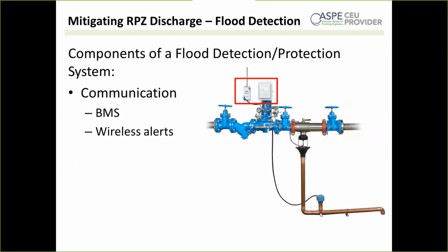Are the shutdown valves FM approved? UL and FM approved. I want to say, I know the one that you're seeing on your screen right now is not. For those of you who don't deal with fire, FM is typically a fire certification. Because I would never personally put a shutdown valve in fire service, I don't necessarily see the need for FM approval. But to answer the question, right now that shutdown valve is not FM approved.